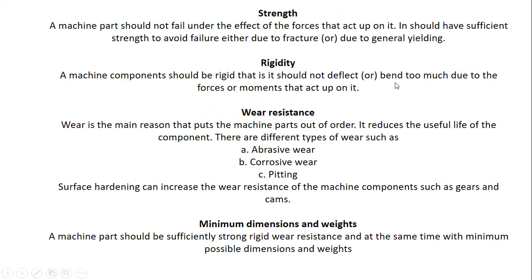Strength. A machine part should not fail under the effects of the forces that act upon it. It should have sufficient strength to avoid failure, either due to fracture or due to general yielding. Does this mean that every machine part will not eventually fail?